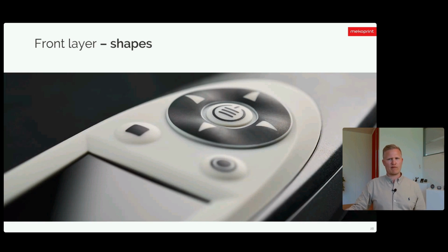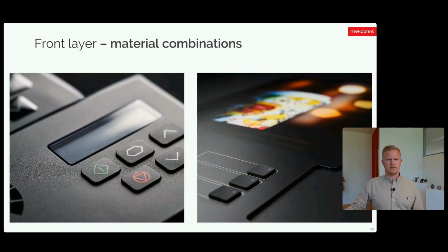And here's an example of a silicone keypad where there's a smooth transition between the keys, but still there's a clear segregation through it by using this level design, but also adding colors. It's also possible to combine silicone keypad with either a front foil or a plate material. This is a good combination because it gives you the graphic advantage of the foil, where, as mentioned, you can add almost limited colors and graphics, and you have the good tactile feedback from the silicone key.